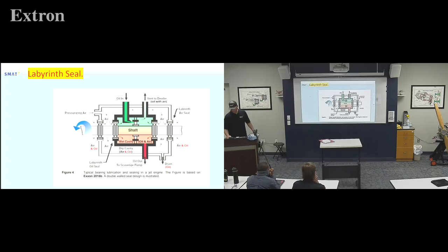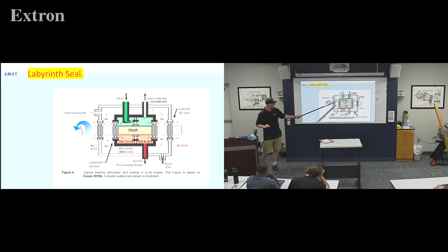If you ever get to where you're touching bearings on a turbine engine, you're pretty deep into the belly. It's probably not happening. So mostly you've got to understand what's going on, why we've got bleed air, why we have the dry sump. They're not something you're going to work on, it's just understanding how the seals work. Why, if we get oil in our combustion chamber, we go, ooh, something must have gone wrong with the seal. Maybe it's all worn out, or maybe our bleed air is not keeping up. So we've got a restricted bleed air or something.